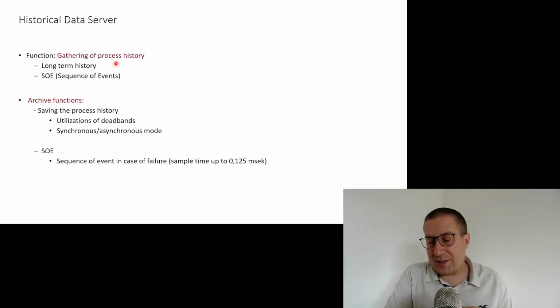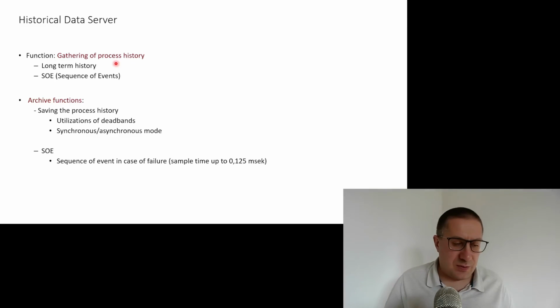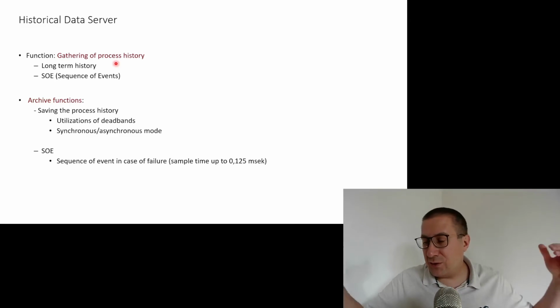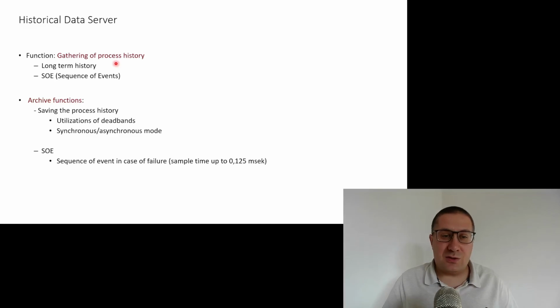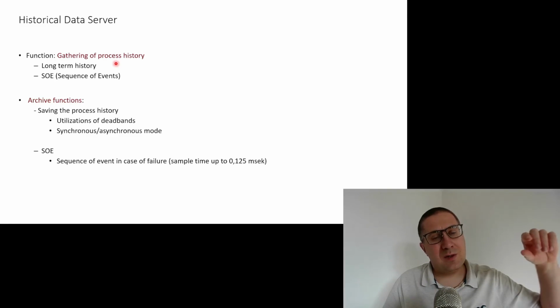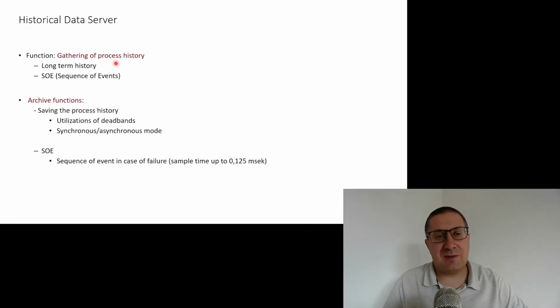Usually such experiments are planned. There are some formal papers that need to be filled in order to perform such an experiment. You have to prepare the whole unit, the whole process, and discuss things with operators. So finally, when you do the experiment, you don't want to wake up in a world where you have lost your data because not all the parameters were defined in the historical data server. So please always double check this.